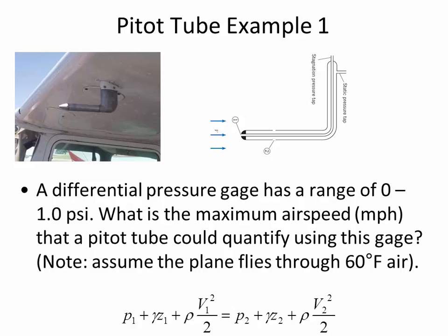It's the pressures. What do we have to do to the pressures to get them ready to use? Yeah, right now we're in pounds per square inch, and so right now we know that pressure at 1 is going to be, in 1 square inch, 1 pound of force pushing on a square inch. But if it's 12 by 12, because there's 12 inches per foot, then there's going to be 144 inches squared per foot squared.